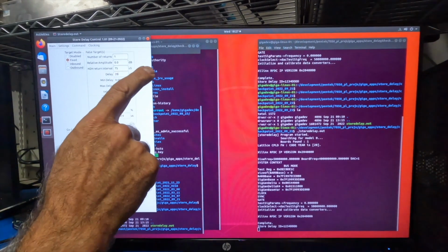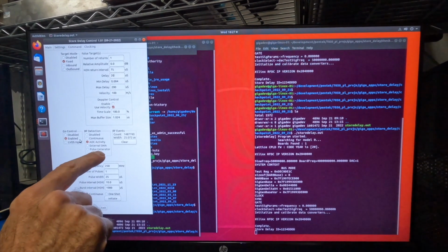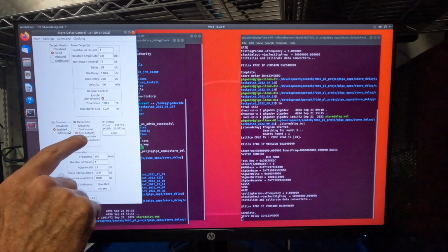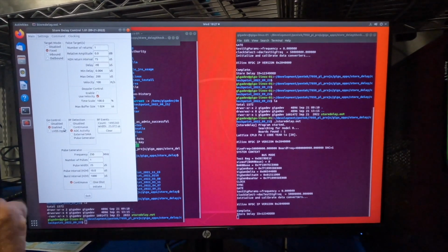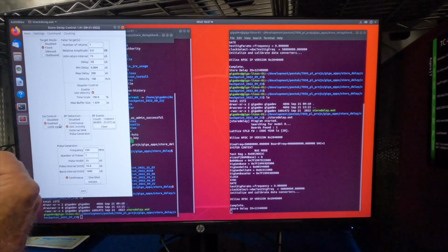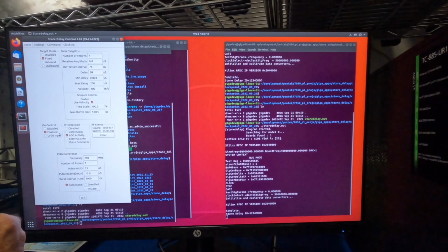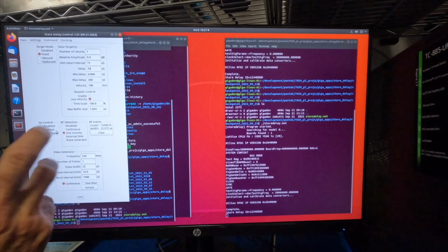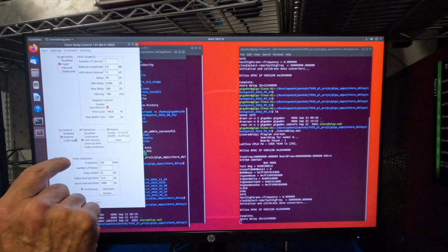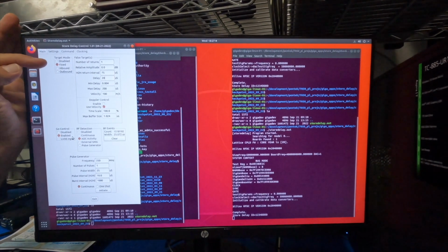sees energy, and how it sees energy is actually selected by how we decide to trigger the DRFM to sample and store the input pulse. For right now, what we're selecting is any certain threshold on A to D activity beyond what typically is noise is going to be assumed to be an incoming pulse. And we would also take an external trigger, say from a video detect log amplifier or some other feature like that. So for right now, we're going to actually sample on the RF energy seen by the A to D. We're going to put out just one return at a fixed range.